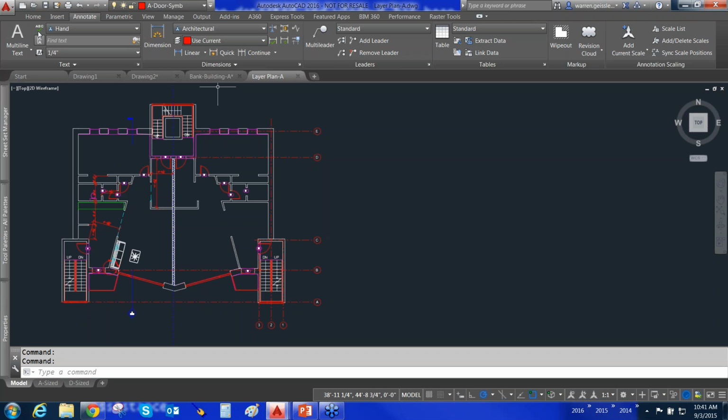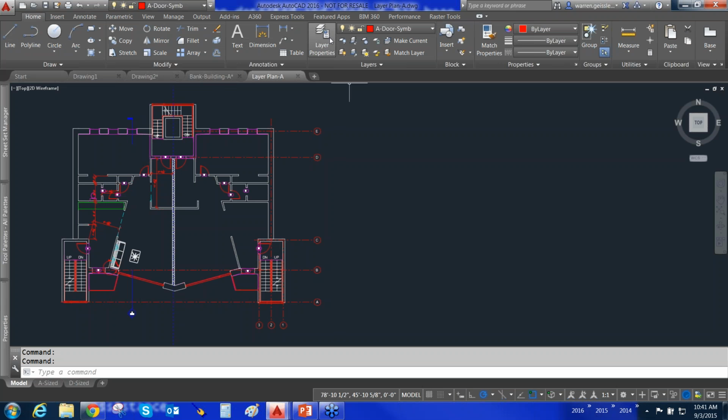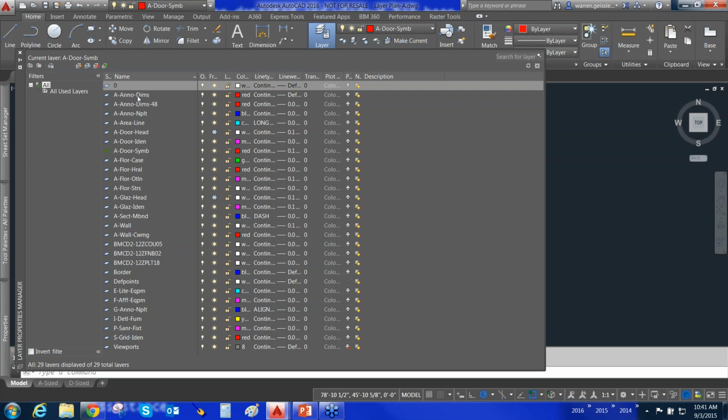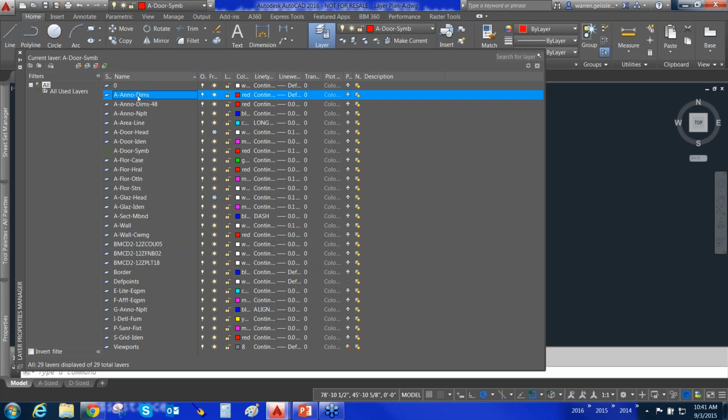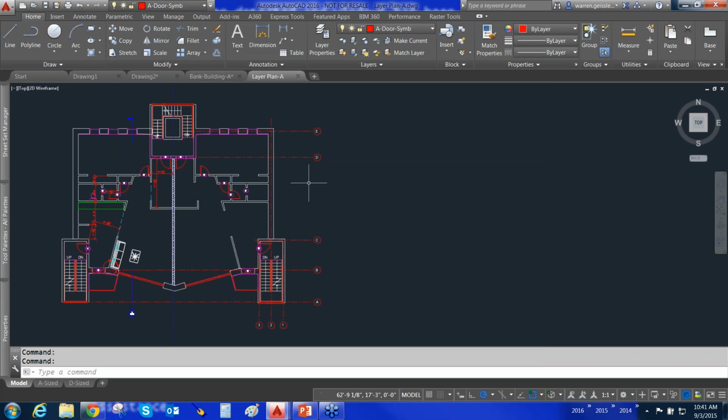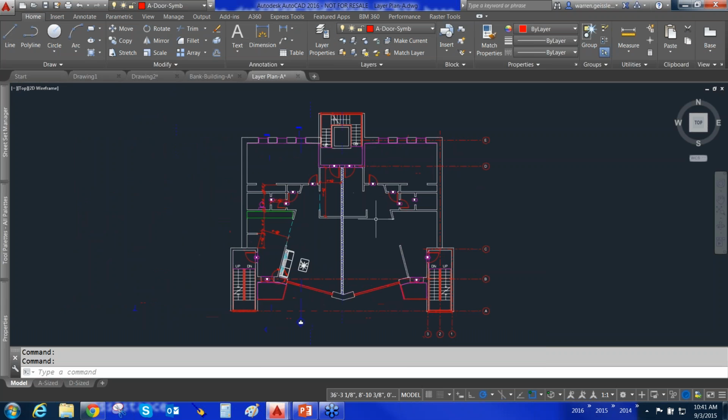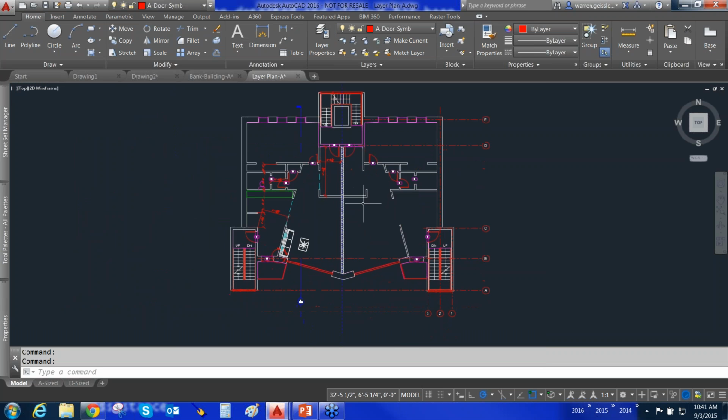Well, renaming layers is really pretty easy. Renaming things in AutoCAD, for the most part, is pretty easy. I can come into each one of these layers in my layer properties, click slowly inside of it or right-click and rename, and type in a new name. And I can do this 200 times. So about somewhere in the 50s, I'm going to want to jump through a window. So how do I take care of that and do it globally? I'm about to give you the answer.